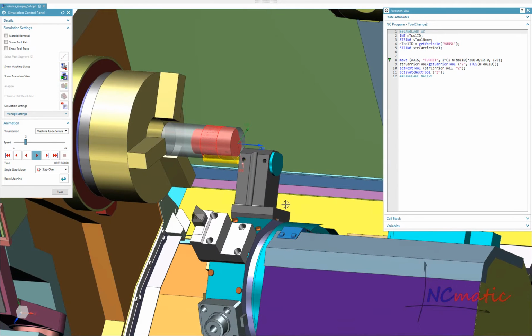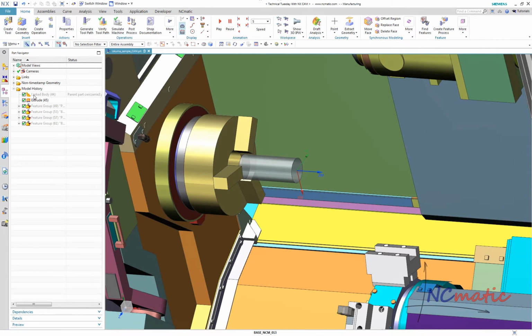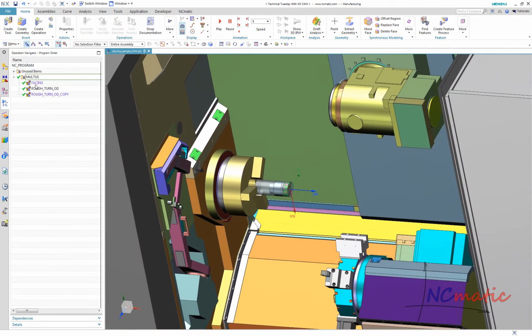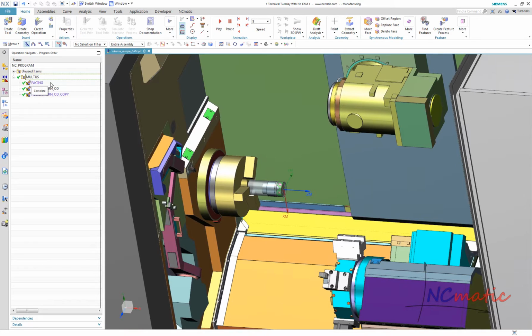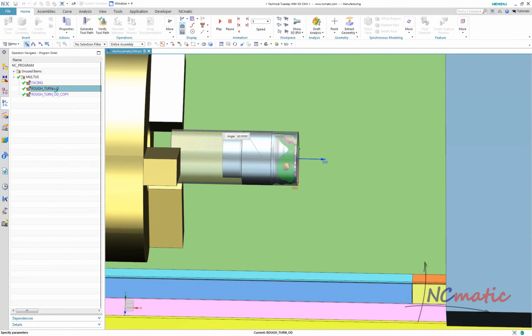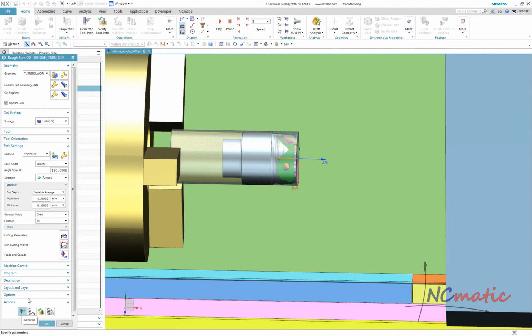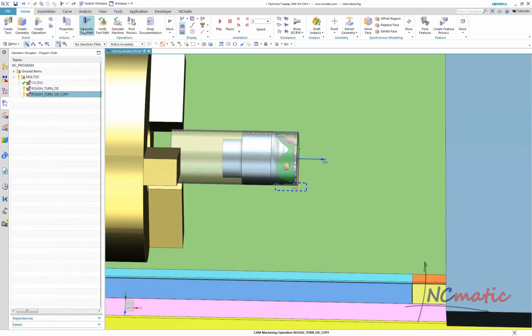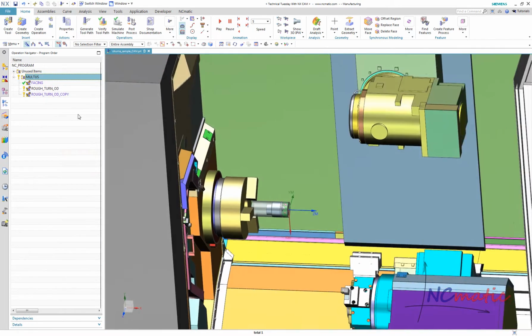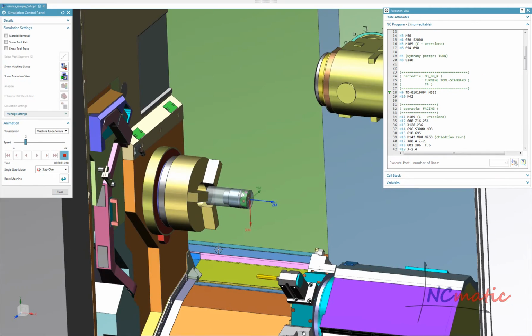Normally, the post-processor outputs a safe retract automatically before tool change, but now I want to show you what options we have to fix it manually. First and most obvious is to modify the toolpath. I will edit the last operation before tool change and make the departure move longer. I will run the simulation again, and you can see that the tool change is collision free now.